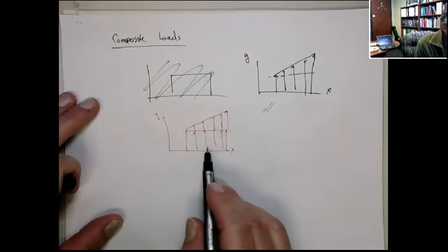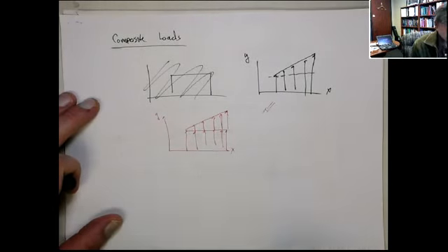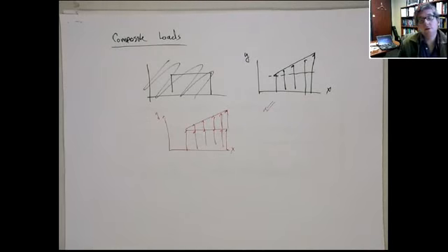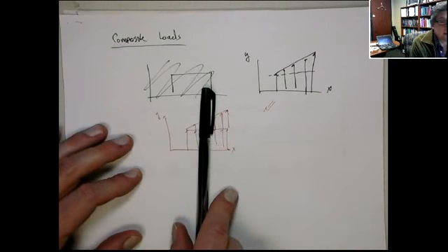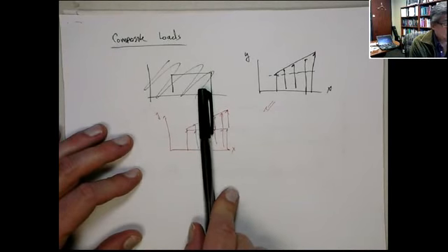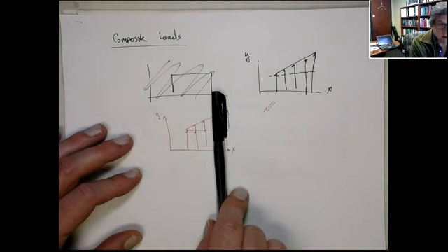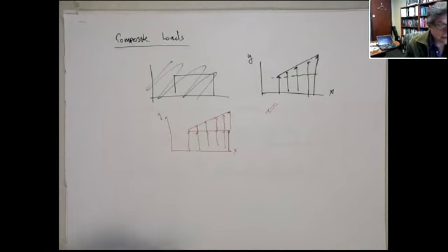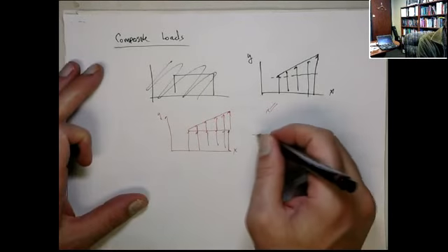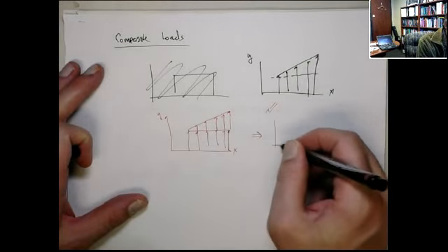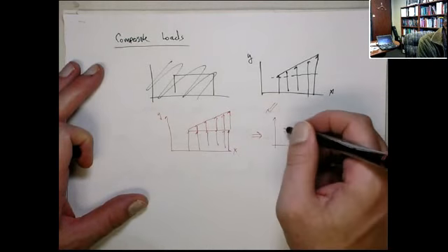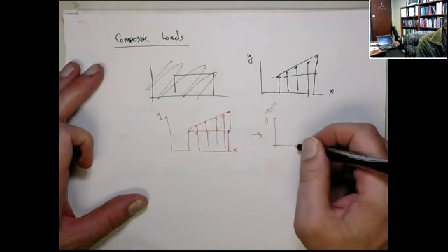So we can make this effectively two forces. You can use the point force of the rectangular portion at its centroid, and then also put a point force at the centroid of the triangle on top of it. So this can be replaced with two forces. And that's fine. You can then combine them if you so choose.